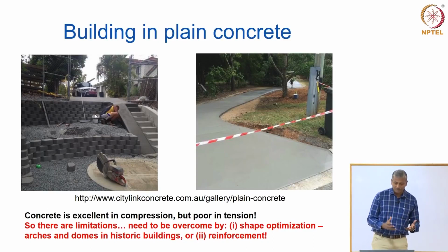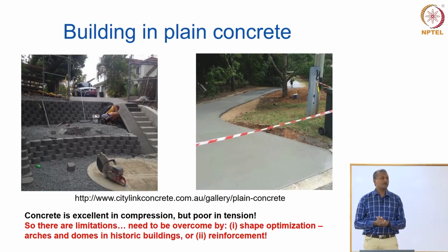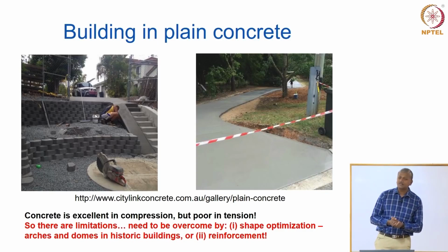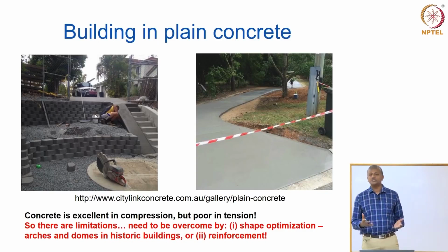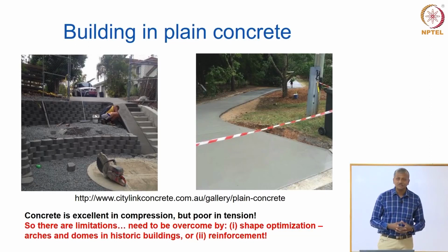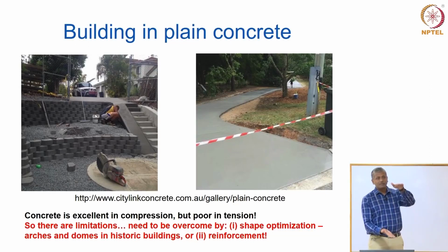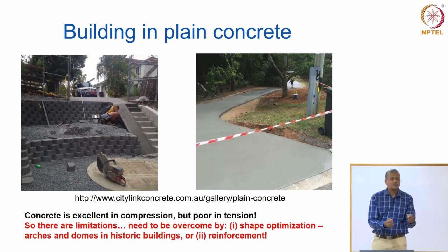But there are obviously some limitations as far as building in plain concrete is concerned, because concrete as a material is excellent in compression, but very poor in tension. What do you mean by compression and tension? Compression is when you are applying the load onto the structure or onto the material. Tension is when you are pulling the structure apart. So concrete is not very good in tension, and because of this you need to strengthen it, right, in tension.